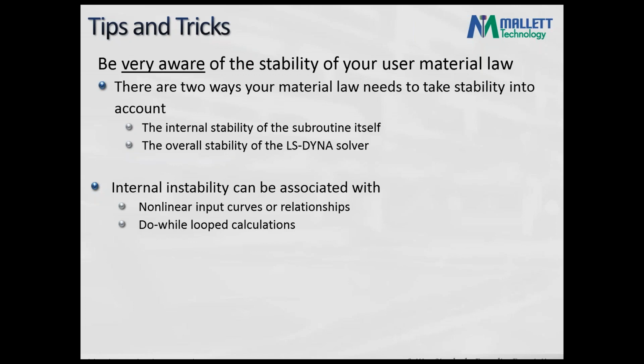The last thing is to be very aware of the stability of your material law. That's something that I have personally run into. You need to be aware of the internal stability of your subroutine and how your custom material interacts with the whole LS-Dyna solver. Internally, if you have a nonlinear input or relationship, an inflection point in your material law, that could pose an issue and should be watched out for. And also, if you're looping within your code, you want to make sure that things don't blow up and have a chance to exit the loop, and so on and so forth. And as to how it interacts with the LS-Dyna solver. Next slide, please.